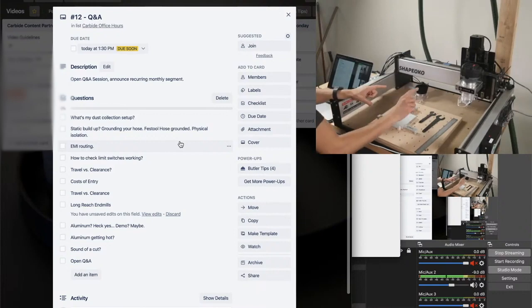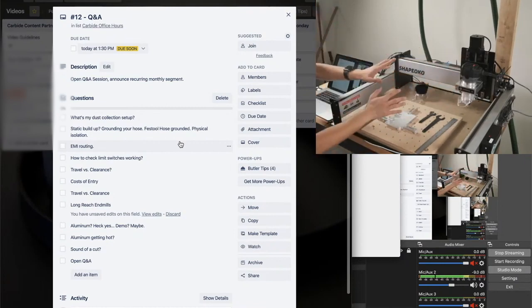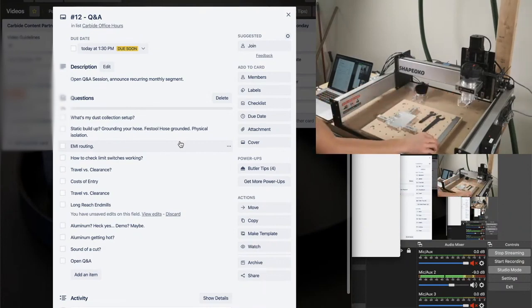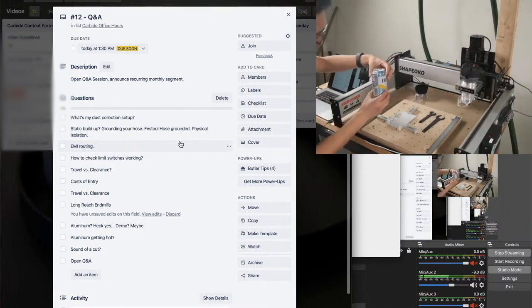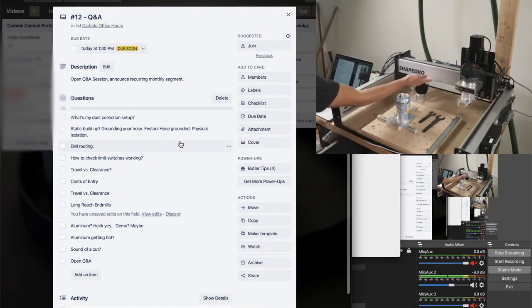So you can fit something taller than 3 inches on the bed of your machine. The problem is not only is your travel limited to roughly 3.25, 3.5 inches, but your tool length also determines what you can machine. I'm looking for something large, and this will do. Let's not show brand names, even though this fine beverage is quite tasty. If you want to machine something really tall, you could, and this could fit under the gantry, theoretically, if I just remove this board. You are limited, practically speaking, by what your end mill can machine.